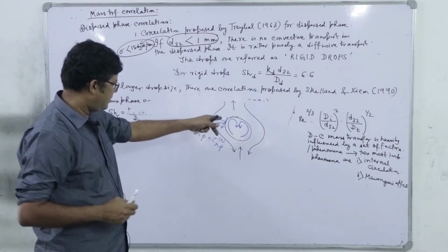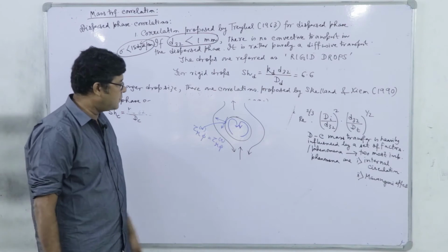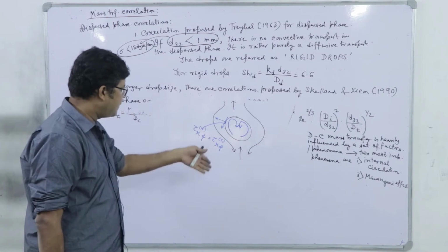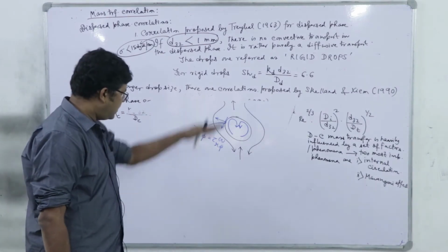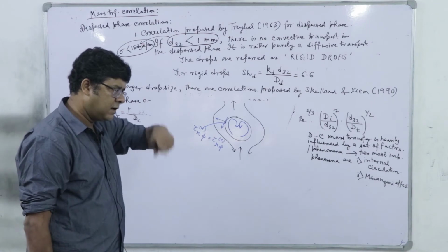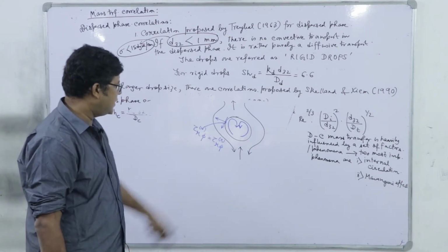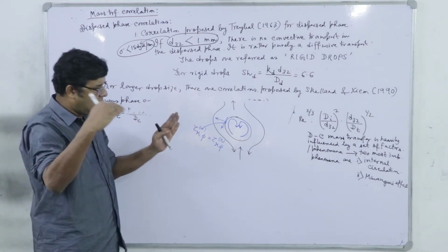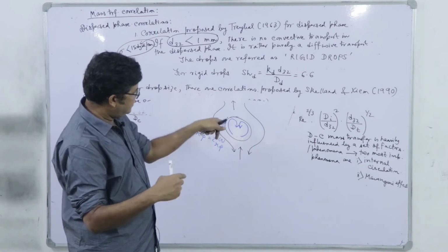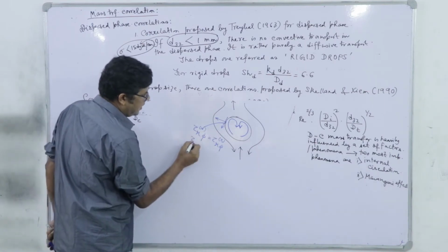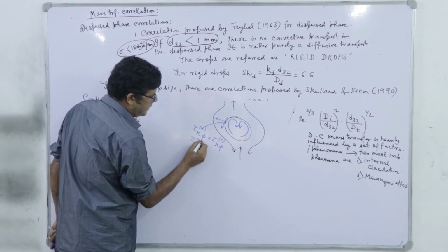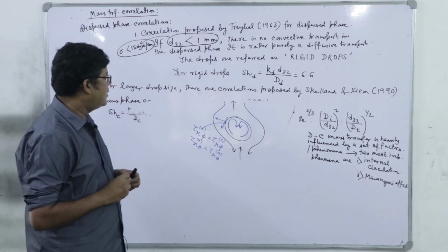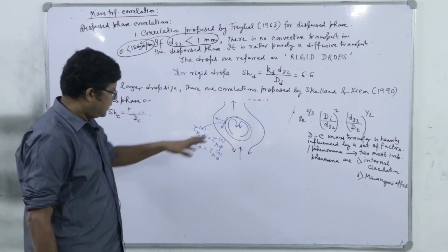The area norm follows the normal direction, and according to the spherical coordinate, phi, the polar angle, follows the longitudinal circle directions. So it is downward, it's tangential. We also have the shear in this direction, so tau r theta of the dispersed phase is also equal to tau r theta of the continuous phase, where theta is the azimuthal angle, according to the choice of the spherical coordinate.